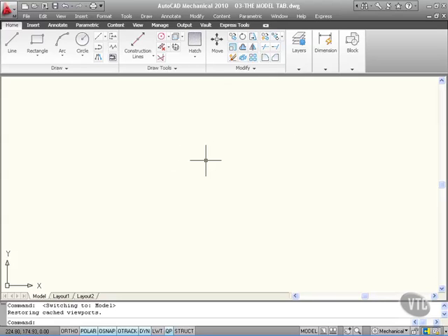And as you can see there, I'm moving around and the coordinates change as per the position of the crosshair. We're using a coordinate driven system, so we're using X and Y coordinates. You'll notice there's a 0 in the coordinate readout that doesn't change. That is your Z coordinate for when you work in 3D, 3 dimensions.